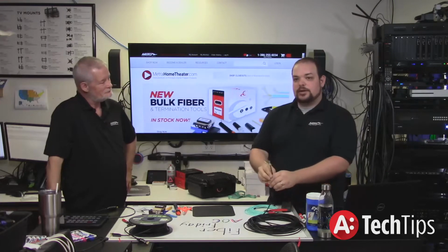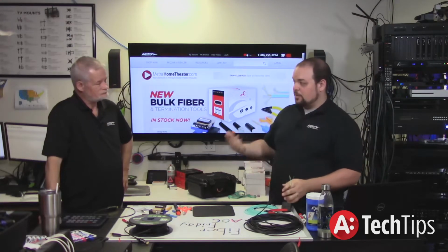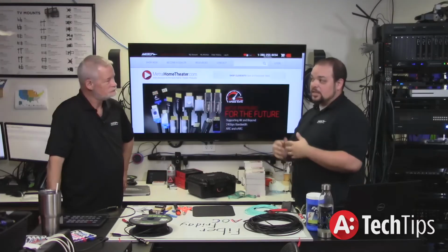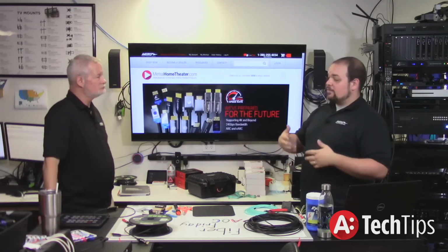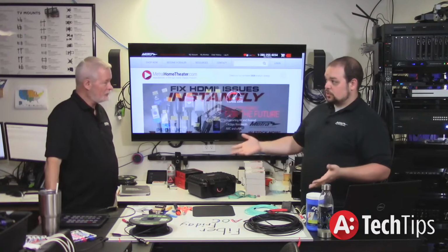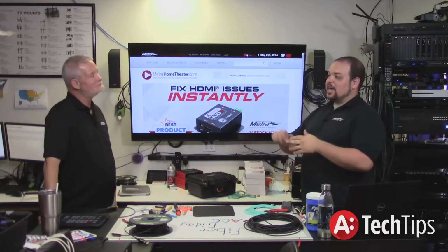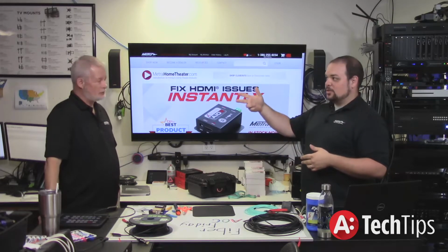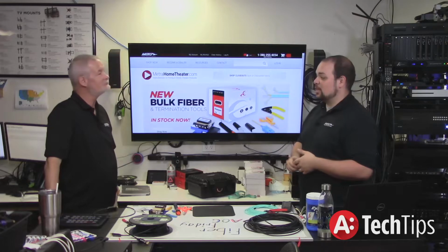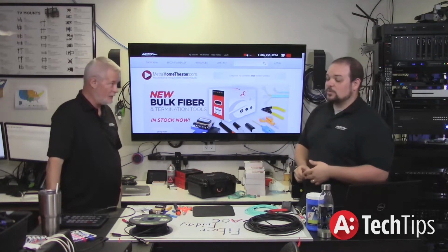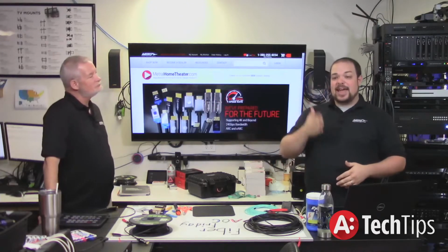So what we're doing here is, when you have a standard HDMI cable, inside of there for the TMDS lines, we have a total of 12 strands. And why is that? Because we have to have send, receive, and ground. It's called a differential system, much like an XLR for the audio guys. So we have to have that for every single channel.